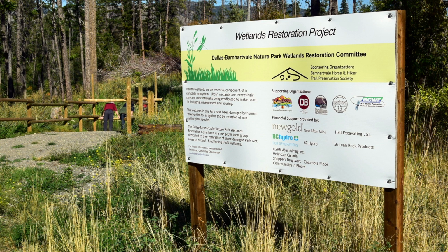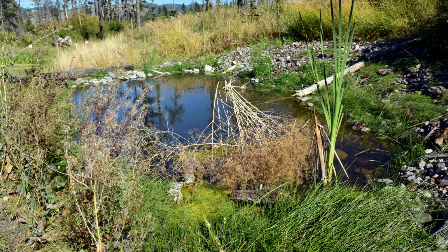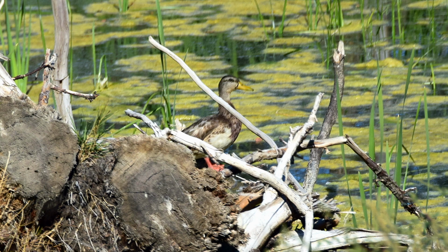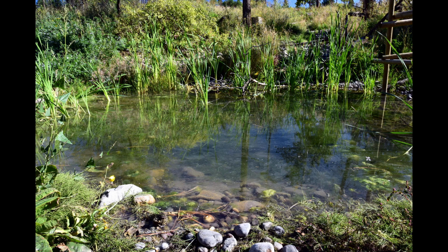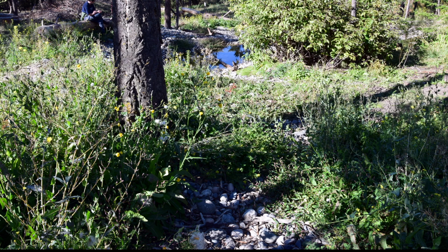Let's see how the wetlands appear less than 1 year after construction. The wetlands are full of water and the plants are growing between the rocks. Mallards were loafing on the root masses we placed in the wetlands. Volunteers had planted cattails in the new wetlands. I have found that cattails can spread and dominate the vegetation in new wetlands unless they're controlled for at least 2 years after construction. We used a large quantity of rock to armor this inlet for the wetland that's on a steep slope. The rock will soon be hidden by vegetation.